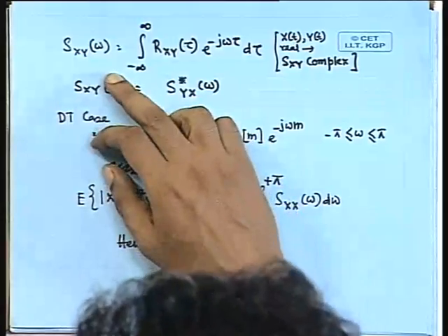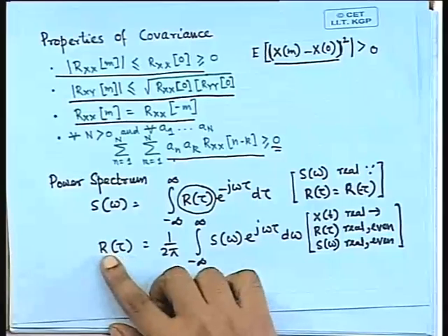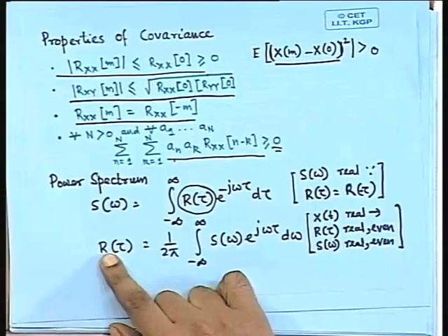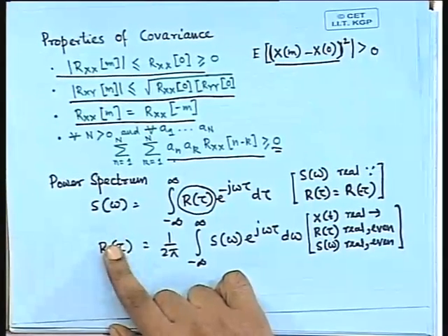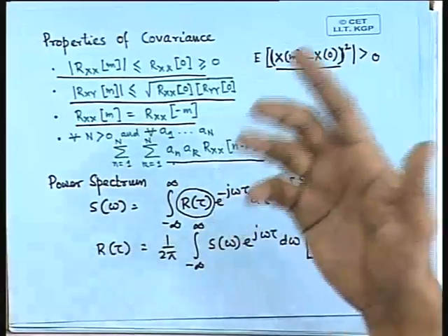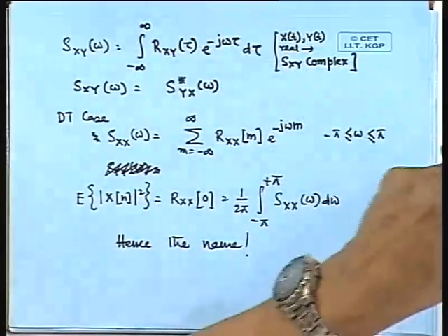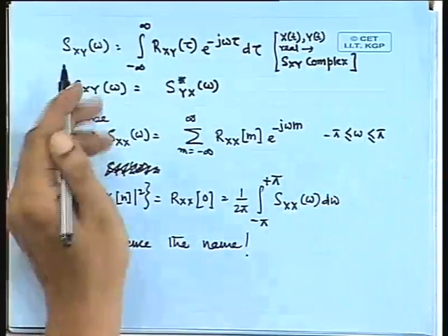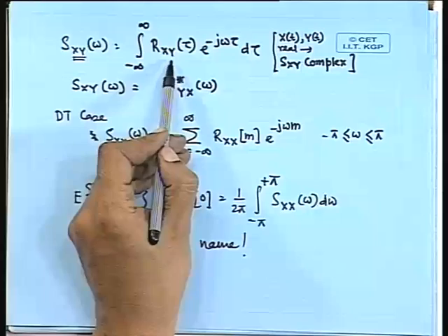Now you have, for example, similarly, so here you have defined this as a general correlation function. Now the question is: this autocorrelation function, this correlation function, is between what and what? You can define it again between x and x, y and y, x and y, various kinds, and so you will get cross power spectrums, auto power spectrums, etc. Various kinds of things. So you can define this Sxy omega. If you are defining a cross power spectrum, then you take Rxy tau.